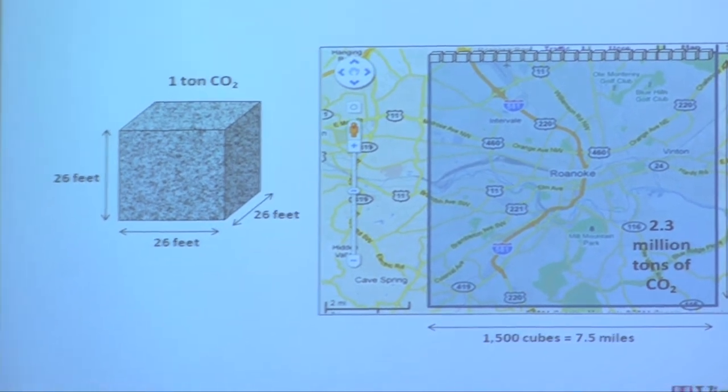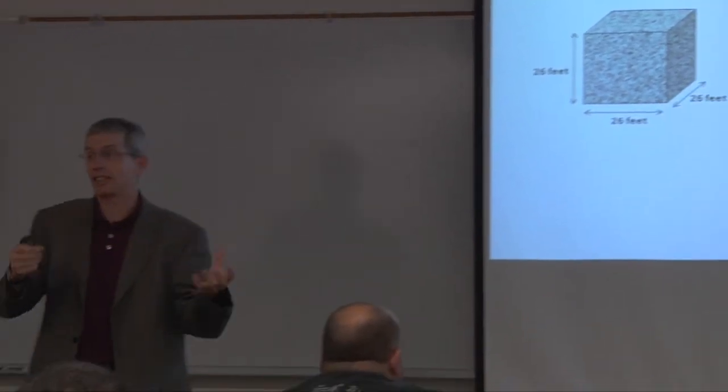But every time you drive a gallon of gas, this is mass in, mass out. A gallon of gas weighs about 6 pounds. So every time you burn a gallon of gas, 6 pounds is being converted into energy, but that mass doesn't go away. It just changes state. So you have about 6 pounds of carbon coming out the back end. In fact, you have 20 pounds coming out because it combines with the oxygen. Right? It turns from carbon to CO2, so you actually get 20 pounds out of carbon for every gallon of gas you use.